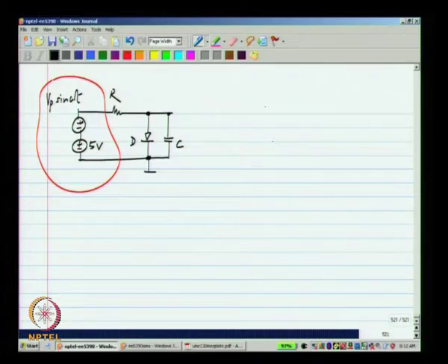Wherever you have either a voltage source or a current source, you can specify the DC value and the incremental values for AC analysis in terms of the magnitude and phase. So, let us say I would want V p to be 1 volt, and I want 1 volt sin omega t.